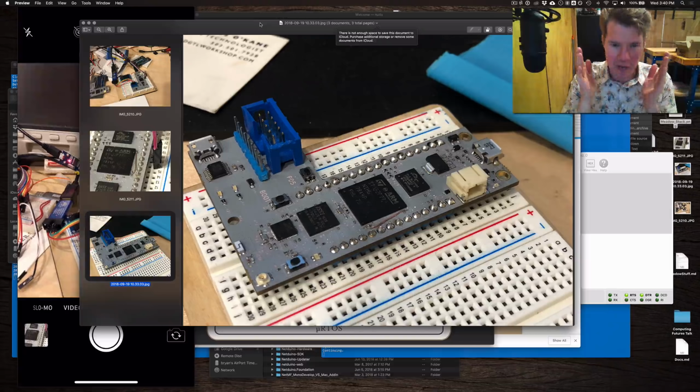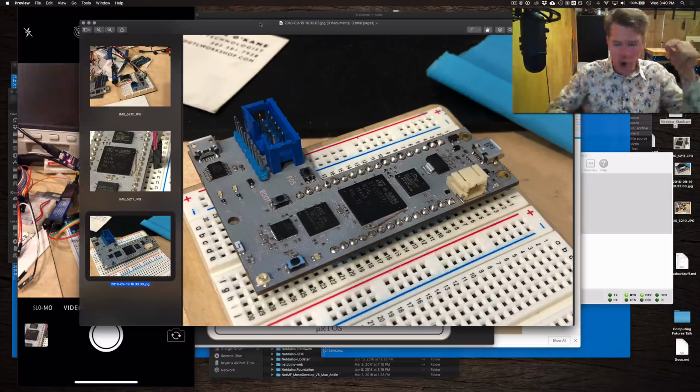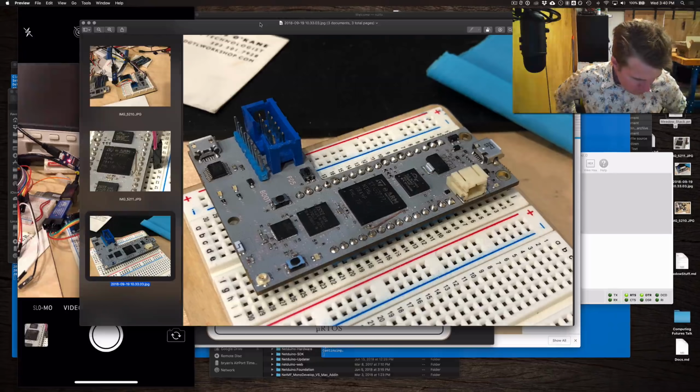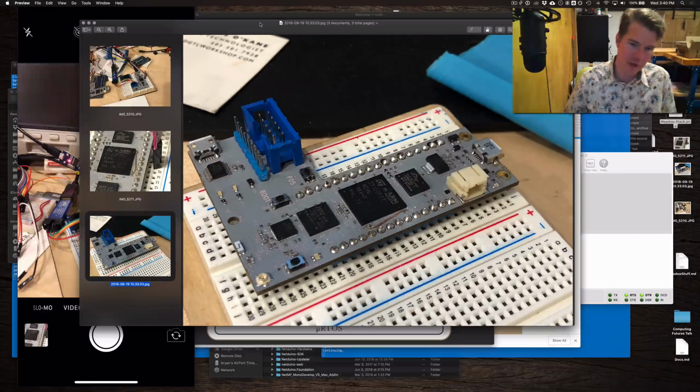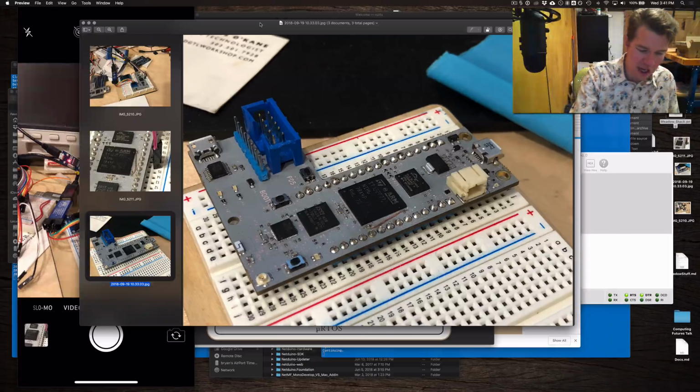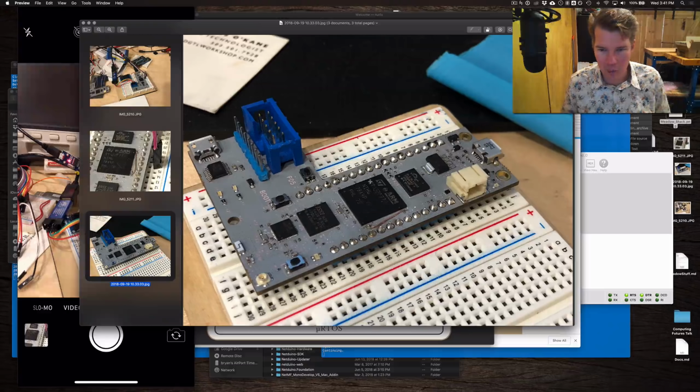And we're checking everything. Power's all perfect. Everything's perfect on the board. We're looking with our oscilloscope and our multimeter, and we're going through this. And it turned out that we hadn't powered the VDDA pin. It was unclear in the data sheet whether or not that actually needed to be powered, and it turns out it does need to be powered, even though we were providing a reference voltage elsewhere. Anyway, I wound up having to solder this little tiny copper jumper between